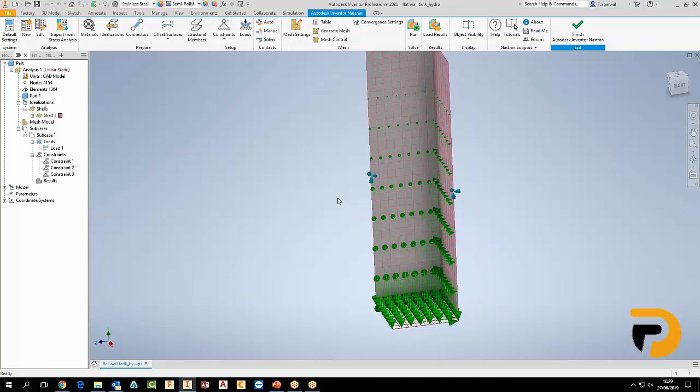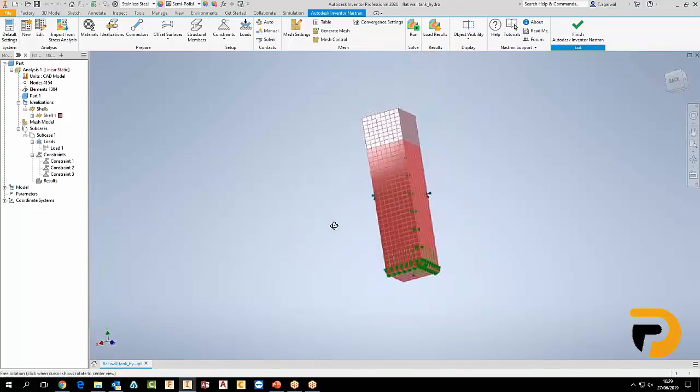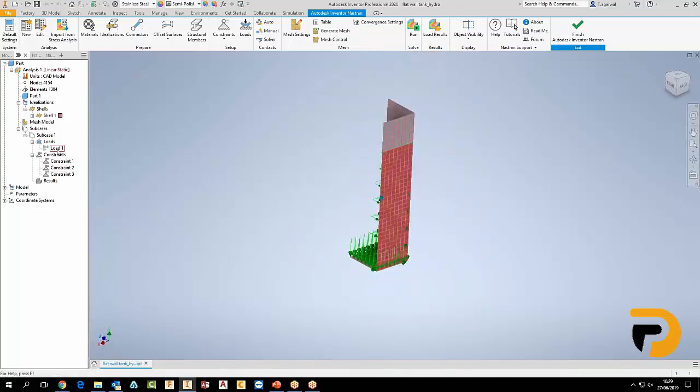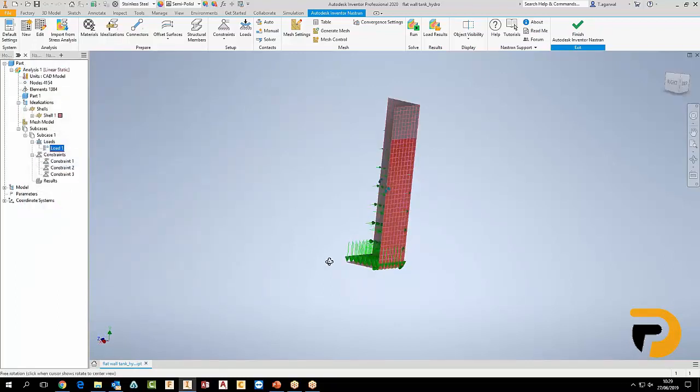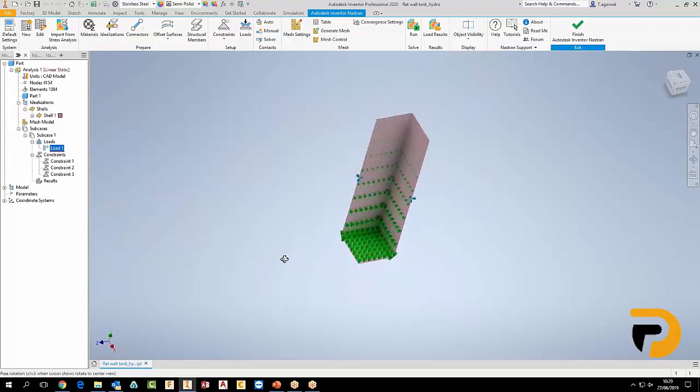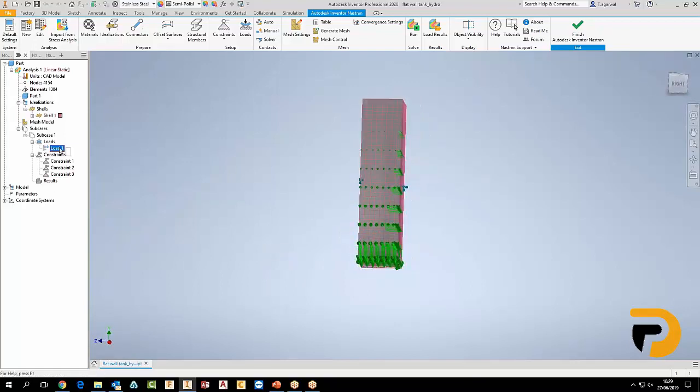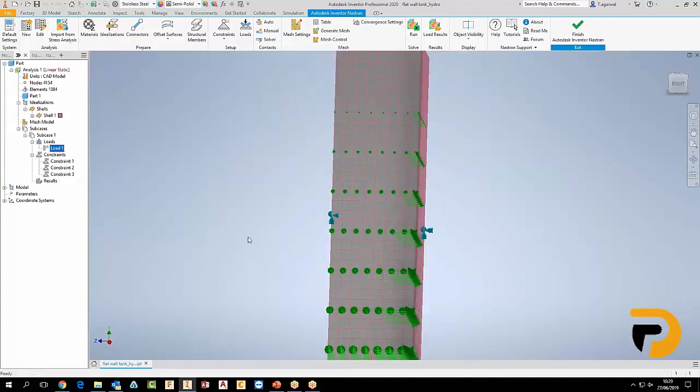Okay. So just to explain what mesh is for people that may not understand, a mesh is very much like a grid. It could be made up of squares, triangles, or just linear geometry. It all depends on the model that you're simulating. If you imagine those little rectangular or square boxes on the model, there is a number of nodes within those boxes that will give us our simulation points and give us our results back. So the more detailed mesh you have, the more accurate result you have. It all depends on the application.